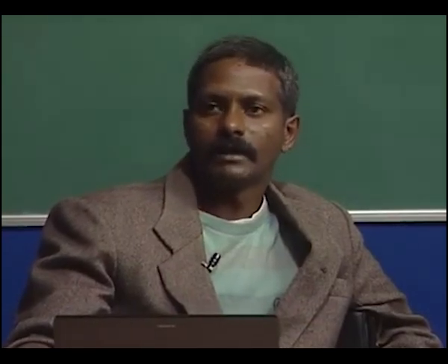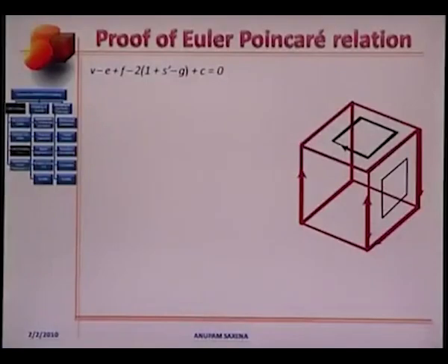If I introduce another boundary component and a loop with it, we are opening up one more face, because of which we actually have 4 faces but 8 loops. Let's verify the Euler-Poincare relation again.